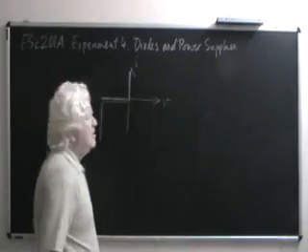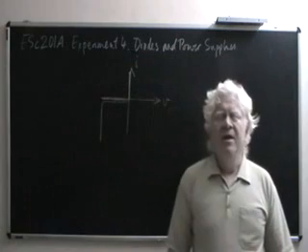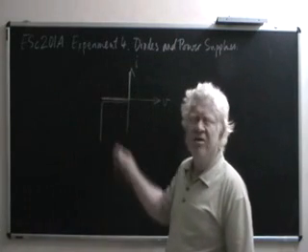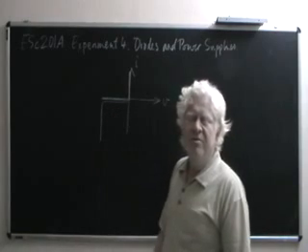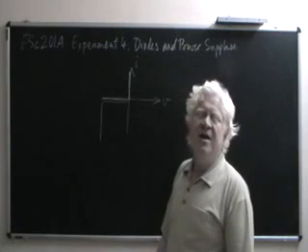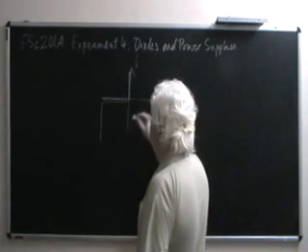In fact, the graph which we are drawing makes no claim to be proportionate. It's only indicative. The reverse currents are of the orders of nanoamps or microamperes, whereas the forward currents are easily in the order of milliamperes, maybe even amperes. So this is up to this point.